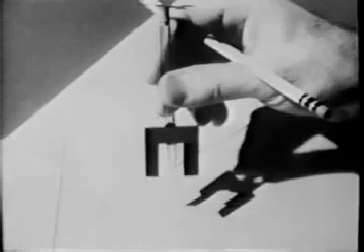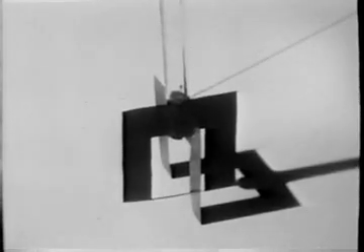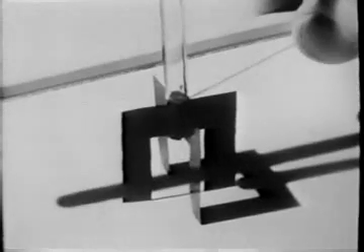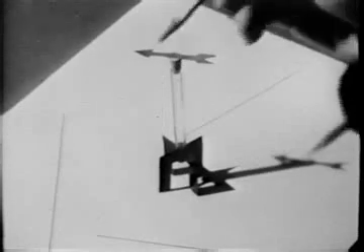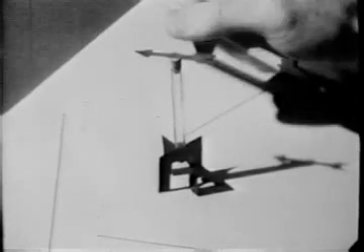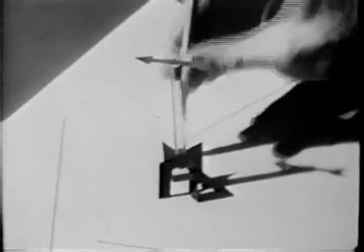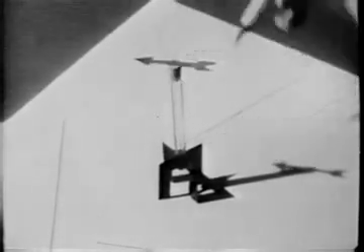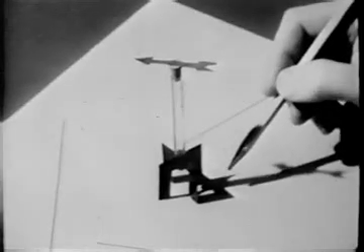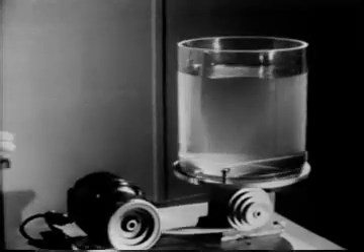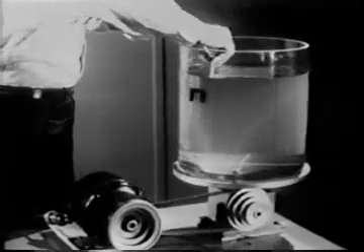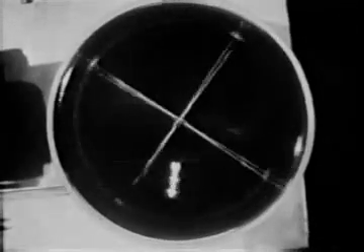This gadget is a vorticity meter, which floats in water with its axis vertical. The two vanes at the bottom are driven by the angular velocities of two mutually perpendicular fluid lines. So the arrow at the top turns at a rate equal to the average of these two. That is, with half the vertical component of vorticity of the lump of water in which the vanes are immersed. This tank has been on the turntable for a long time, and viscosity has forced the water into a rigid body rotation. The vorticity float rotates almost exactly with the speed of the crossed white lines on the bottom of the tank.